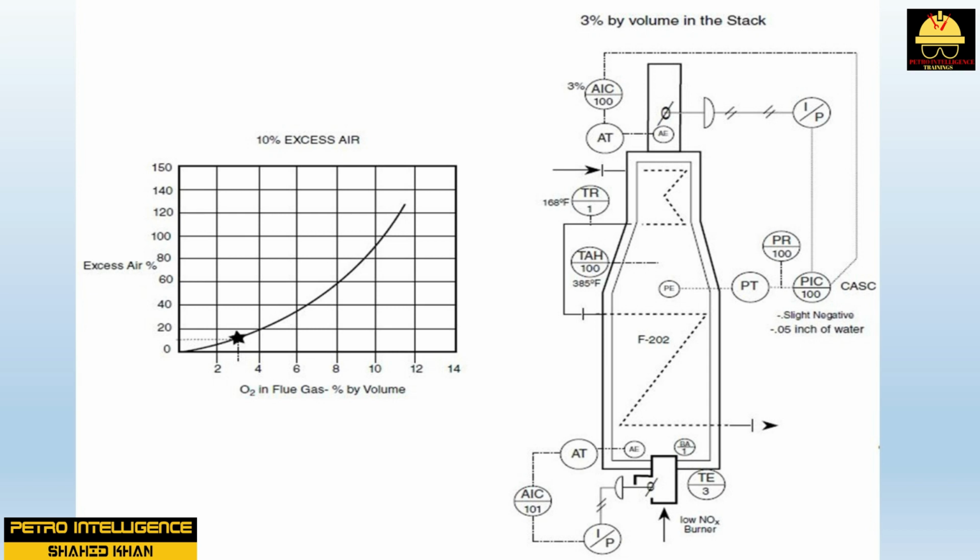Air-to-fuel ratio. Unit specifications require the console technician to decrease the excess air so that temperatures in the process heater will increase. As the excess air is decreased, the heat transfer rate near the burners is increased. Because the net heat released from the natural gas burner has not changed, the amount of heat contained in the hot combustion gases slows down and has time to soak into the exposed tubes.